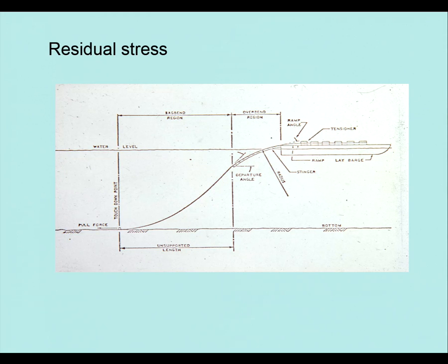Yeah. And I think for the thin wall and thick wall, the assumption is that for the thin wall we have a plane stress condition, and for the thick wall we have a plane strain condition. But I think for the subsea condition, when we have external pressure, even if we have a thin wall pipeline, the expansion in the radial direction is actually restrained because of external pressure. Do we consider that situation like a plane strain?